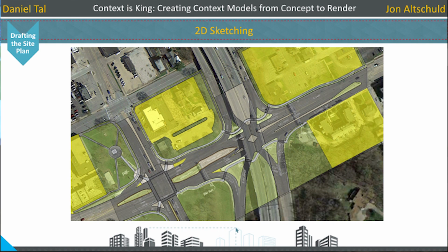There's not a lot of straight edges here. It's mostly arcs. Always set the arc tool. The arc tool and the circle tool automatically default to 12 faces. Who knows what I'm talking about here, right? Yeah. Set that to 60 to 100. You'll pay the price later for it in some form, I'm sure. But you're going to get much cleaner edges and the ability to actually draft that out using a more faceted, high-faceted arc system.